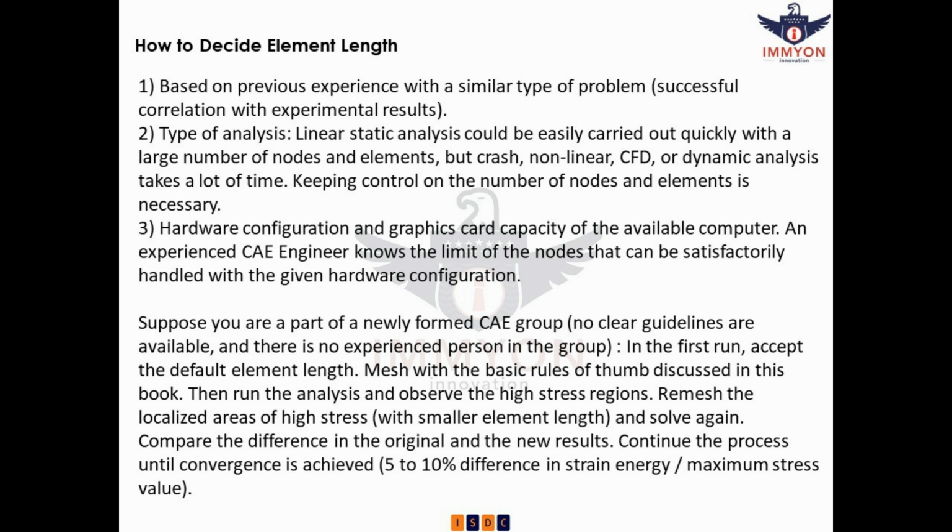How to decide element length. 1. Based on previous experience with a similar type of problem, successful correlation with experimental results. 2. Type of analysis. Linear static analysis could be easily carried out quickly with a large number of nodes and elements, but crash, nonlinear, CFD, or dynamic analysis takes a lot of time.